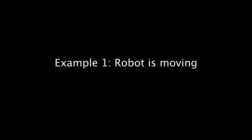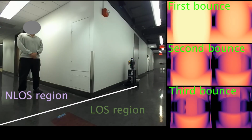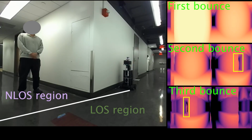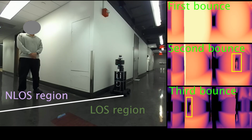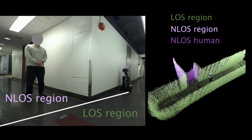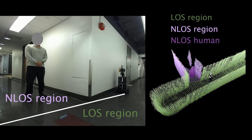In this example, the robot is moving while the person remains stationary. On the right, we show our multi-return RF imaging results. Yellow boxes highlight the human in the non-line-of-sight image. Even though the person is hidden, our second and third bounce reflections successfully capture their presence. Here are the corresponding 3D reconstruction results. The non-line-of-sight geometry and the hidden person are clearly revealed.